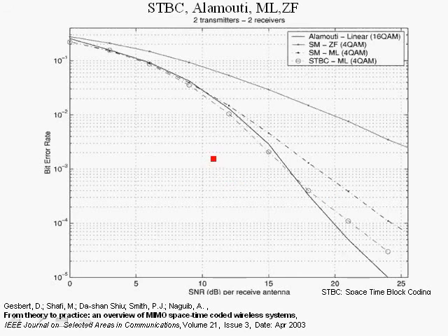We will present many other plots, and we have previously presented plots that show that the Alamouti scheme achieves a great performance over SISO systems and also in many cases open loop MIMO systems depending on the conditions. And here we clearly show that it has an advantage over even a 2x2 maximum likelihood MIMO open loop system.